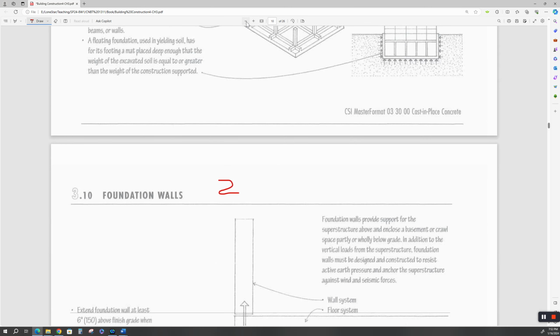Okay, here's a side detail. It's a typical stud wall framing. There's your anchor bolts that are set in place when they cast the wall. And there is your sill plate. And yes, it better be pressure treated. And then there's your header or rim joist. And there's your floor joist. And then there's your substructure framing, whether it's wood or steel.